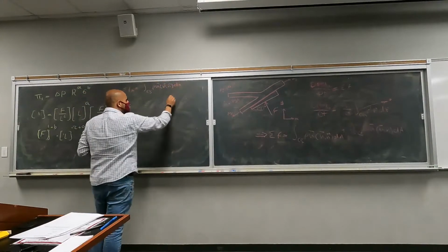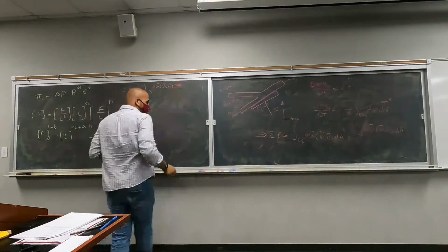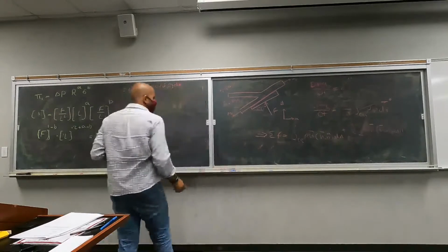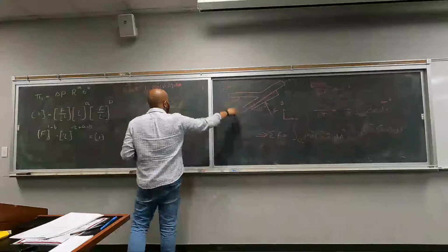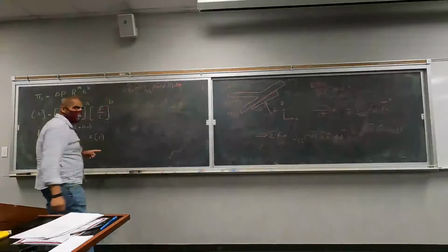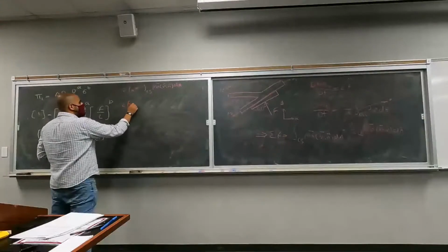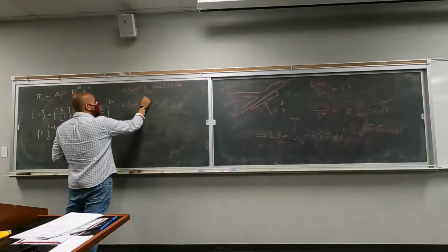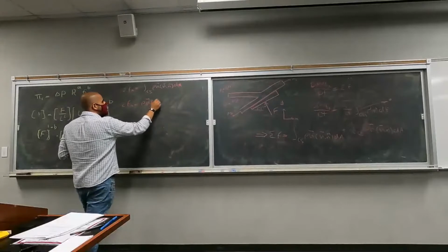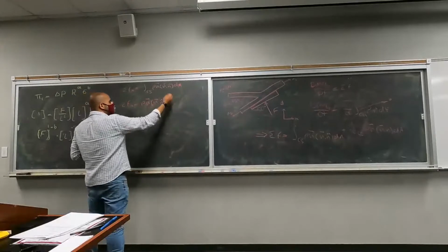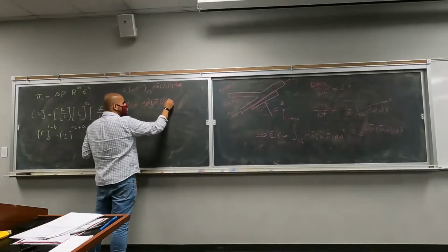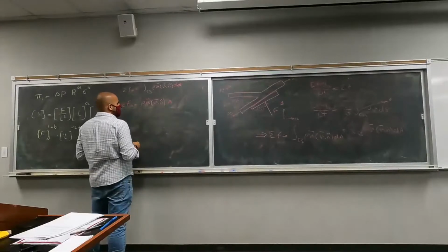We can write the same thing for the other direction. The idea here is that all of these velocities are constant. The same is true for density. So we can take them out of the integral. Fx is rho v vn, and the integral of dA is going to be A for all of these three surfaces.